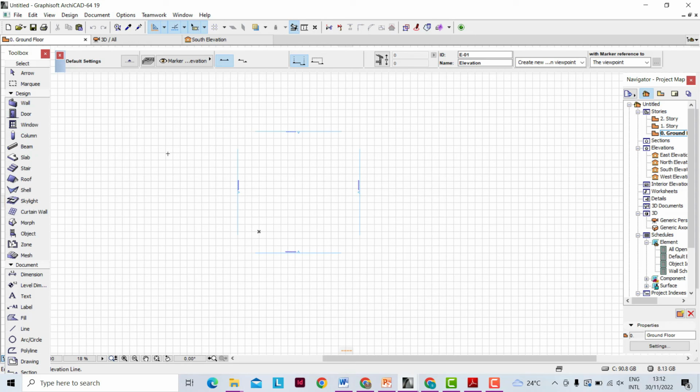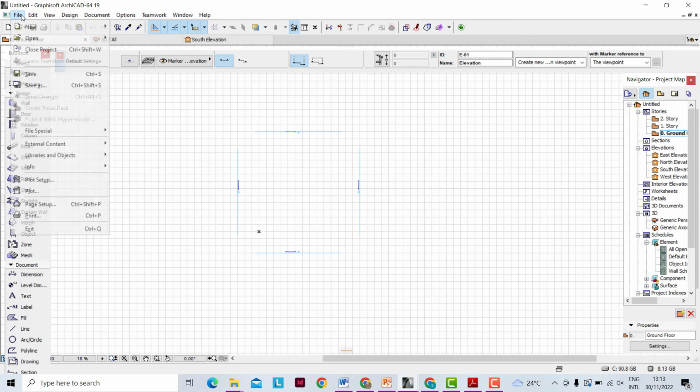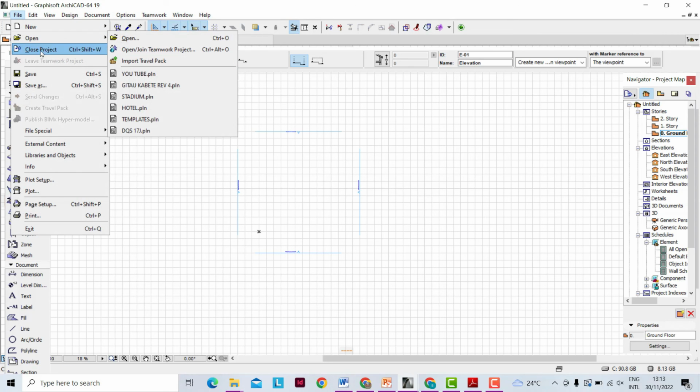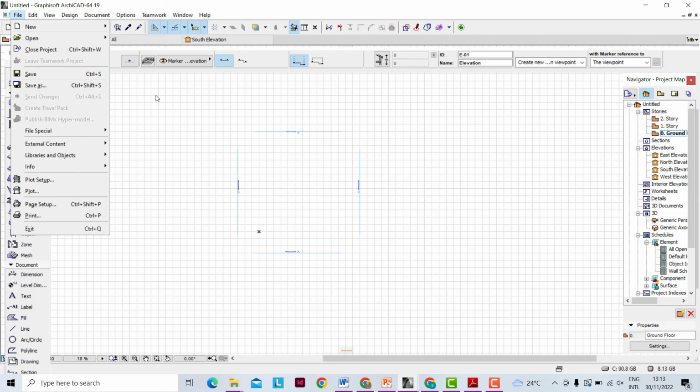So those are quite a number of things that I wanted us to look at under the workspace for ArchiCAD. But maybe before we wind up with that section, it's worth mentioning that in ArchiCAD we also have another shortcut bar, where we are able to get the same commands that we saw, like in file we have save as. We are able to get those commands here.